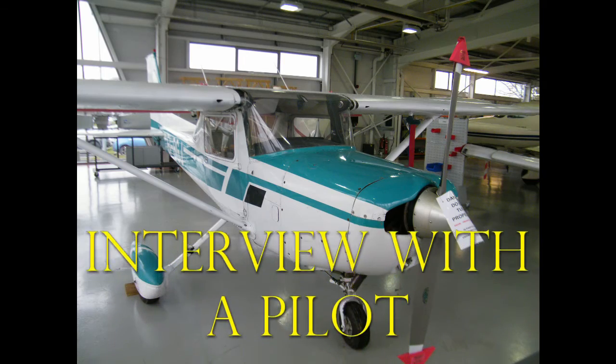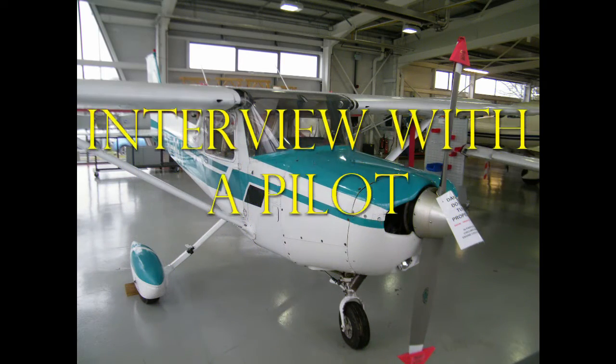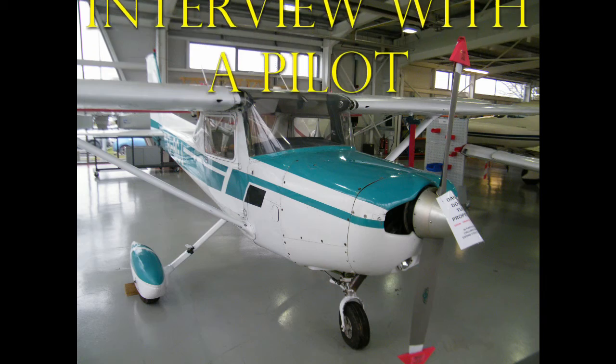Here are a few clips from our interview with Mr. Peter Taus, a local motor glider pilot and instructor. What are the dangers of wake turbulence? The wingtip vortex results in a rolling motion. So the primary risk at low altitude is loss of control, and particularly an uncommanded roll.